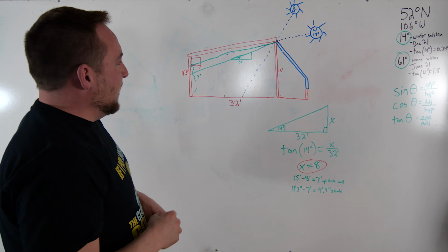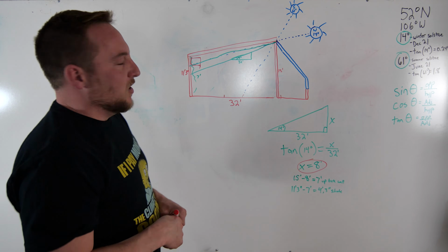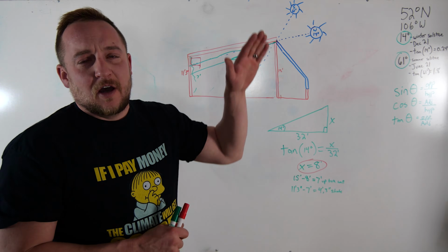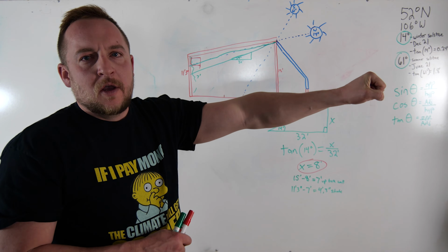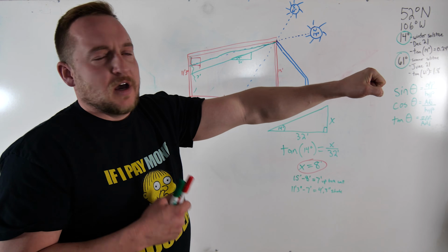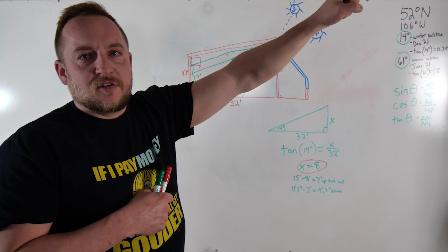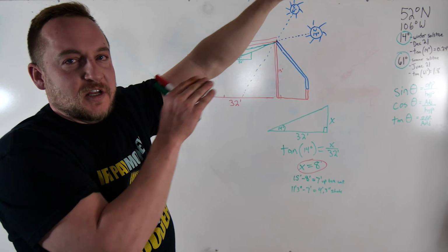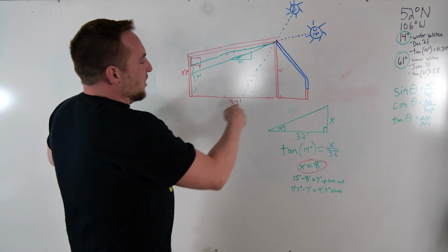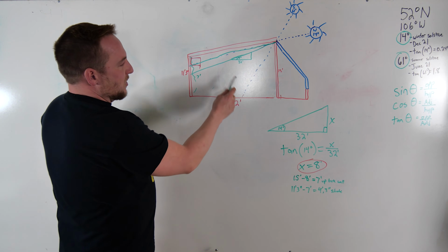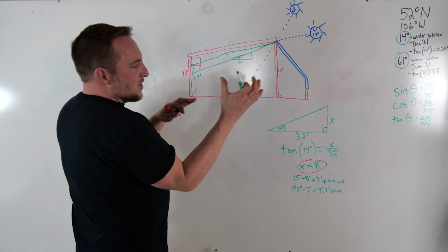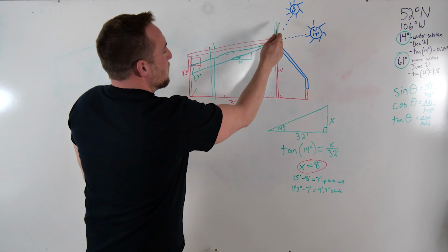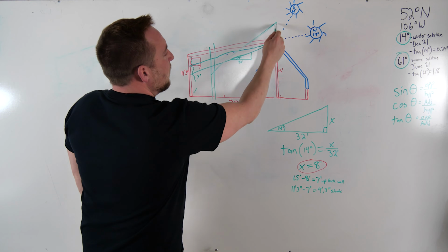Now, if you are in a different part of the world, so further south than us, 14 degrees at the winter solstice is very low. So if you're in, I don't know, Montana, North Dakota, Arizona, your winter sun is much higher, so you wouldn't go as deep. You wouldn't have a deep winter greenhouse. Maybe you'd adjust mine. This works for me. Maybe your back wall would be here, or you could raise this up more and have a bigger angle.